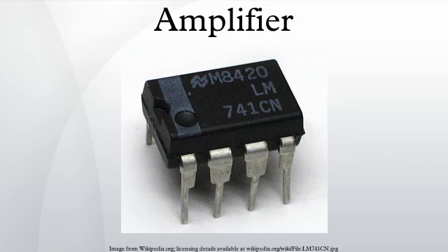This design is simple, but a good basis for a practical design because it automatically stabilizes its operating point, since feedback internally operates from DC up through the audio range and beyond. Further circuit elements would probably be found in a real design that would roll off the frequency response above the needed range to prevent the possibility of unwanted oscillation.